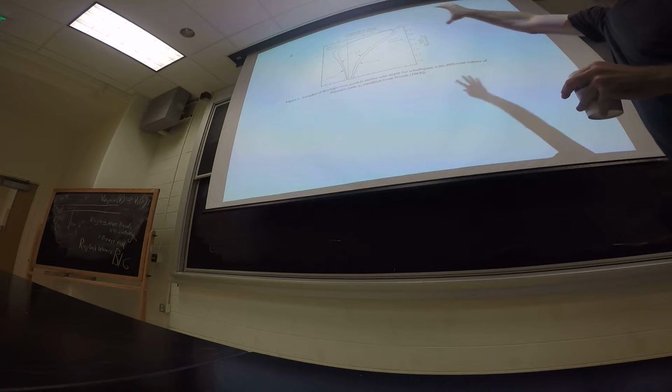On the vertical axis, what we've got is depth over wavelength. So this is for a particular wavelength or a particular frequency. Okay. So what you can see is that the Rayleigh wave is large up to maybe a half of a wavelength. And beyond that, it really decreases in amplitude. So what does that tell you about how deep?